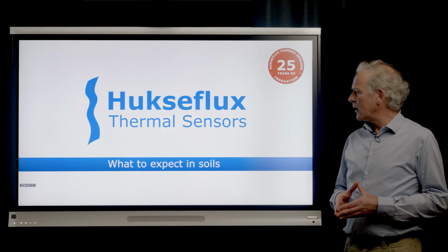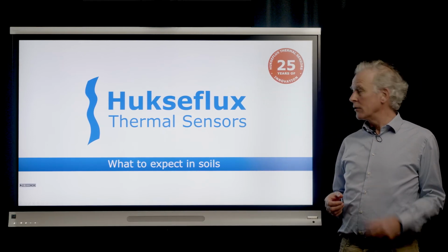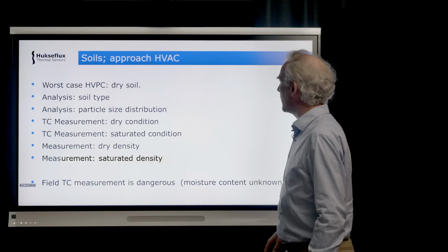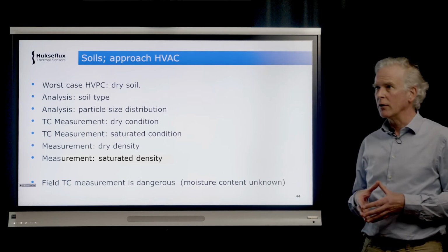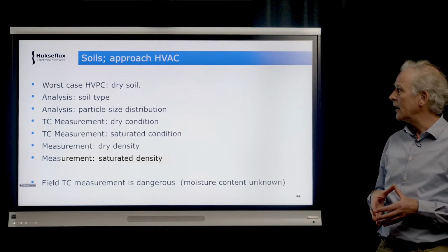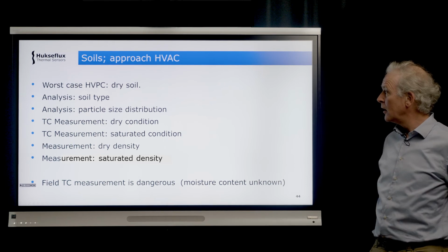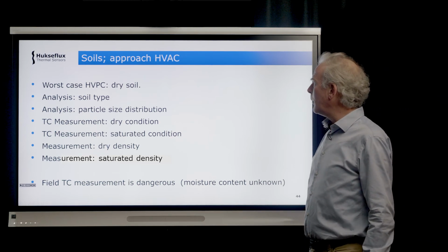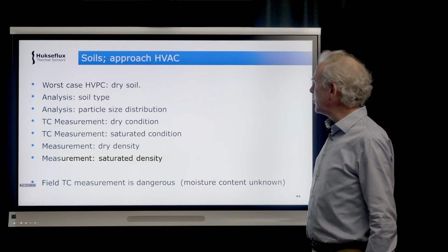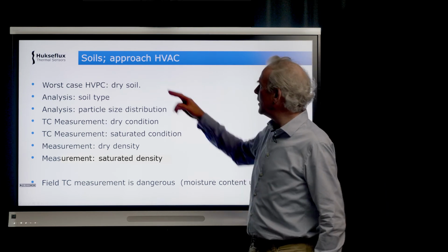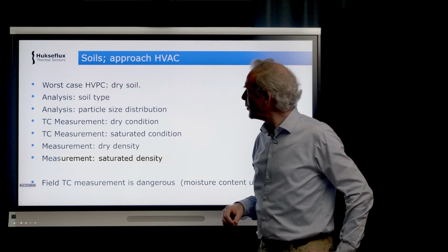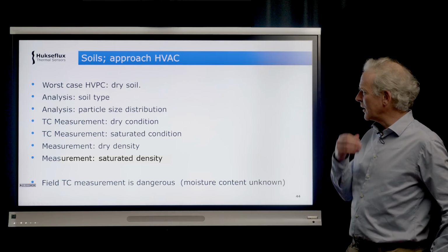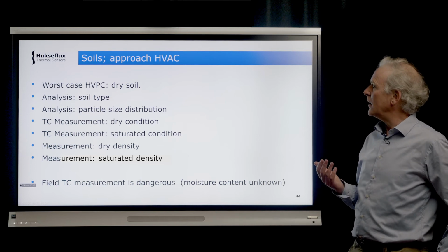So, last subject: what can we expect in soils? You perform a measurement, and the question is, what kind of results can realistically be expected, or how to approach the whole measurement. One thing to keep in mind: in high voltage power cables, a perfectly dry soil is considered the worst case situation.